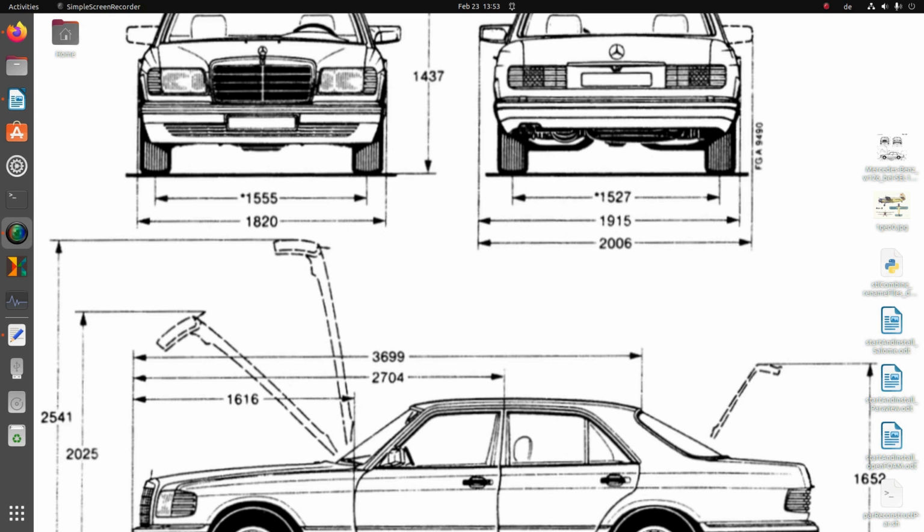Generally, this calculation is based on the motorbike tutorial, so you can also watch the motorbike tutorial if needed. The simpleFoam solver is used for the calculation. Let me show you the description of it from the internet.